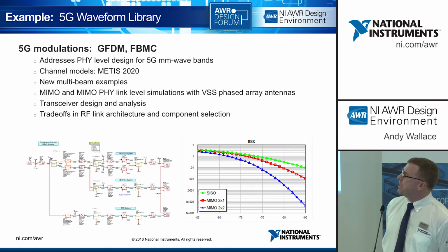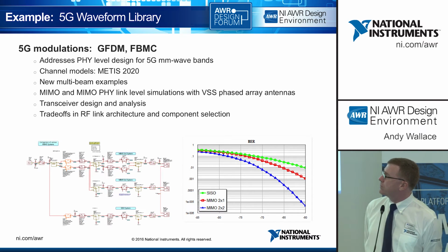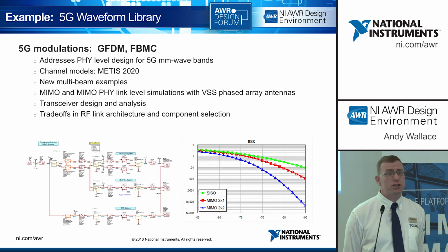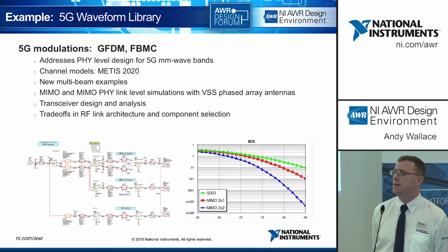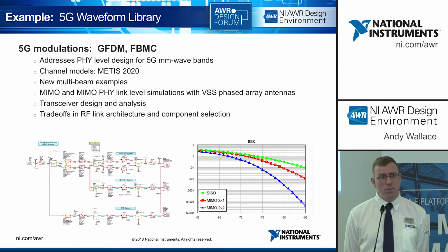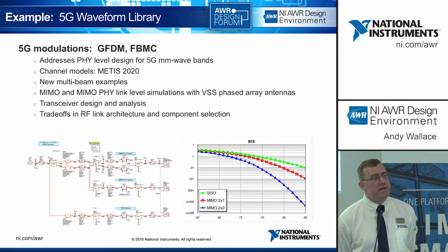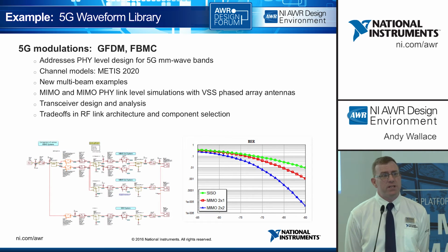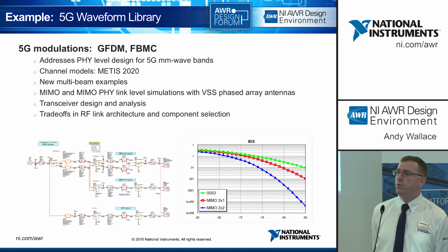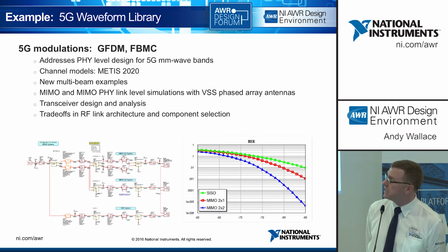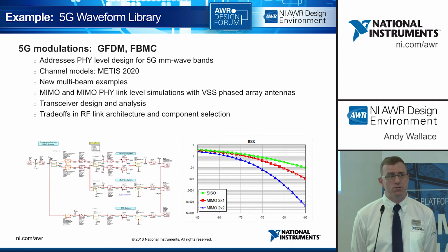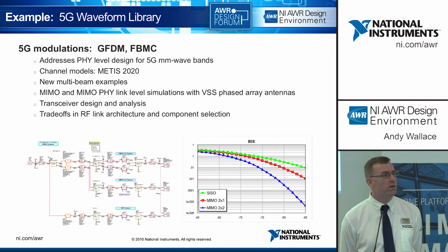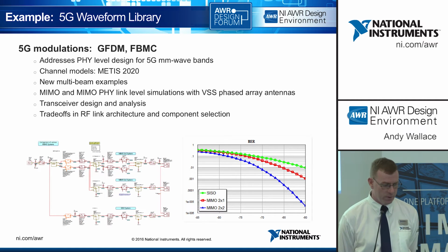VSS as a systems simulation tool can get as complex as you like. This is a quick screen grab of a particular 5G modulation scheme being generated, looking at the bit error rates, the different types of modulation, algorithms that can be used and the trade-offs, very appropriate for some of the MIMO applications. And as you might know, as a subset of National Instruments have USRPs, radios that can be programmed from LabVIEW. Now you might appreciate that LabVIEW and VSS will run side by side, but of course these signals we generate in VSS can directly drive PXI hardware, and that includes the USRP radios as well for MIMO work.